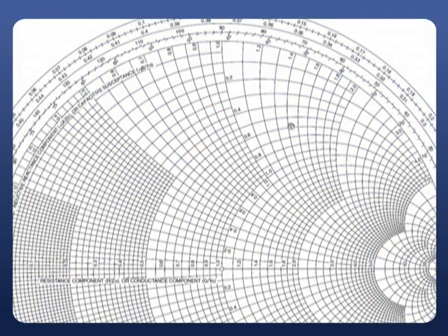Now, with that one, I will start our problem. On our Smith chart, let us consider this point. This point always represents R is equals to 1 circle and X is equals to plus 1. So, this may be 1 plus J1 ohms as the load impedance, that is what I am considering.